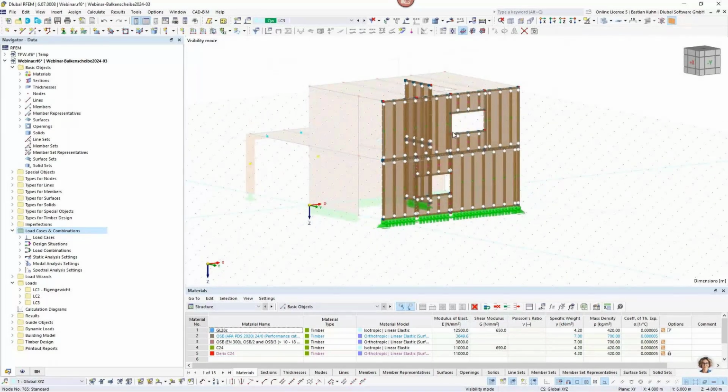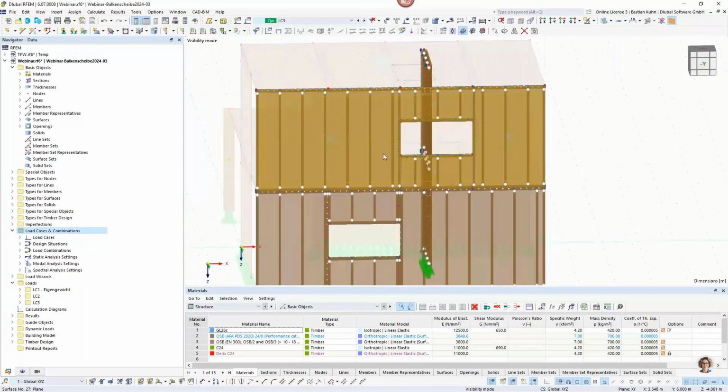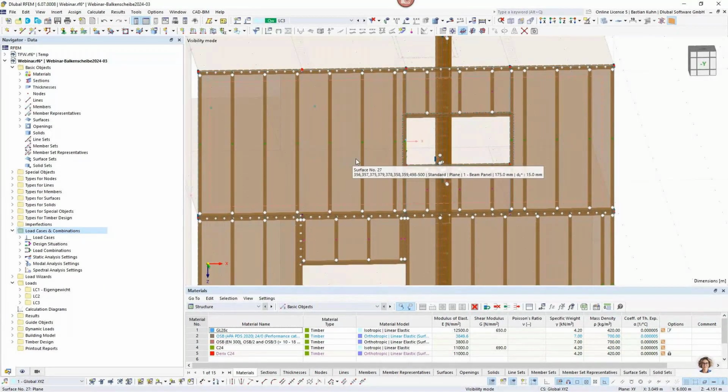But anyway, okay. So now we look at the top wall first, and we see that the distribution of the beams and posts is quite good. We would calculate the opening, and it kept our spacings of 625 millimeters in between, and here we have a middle value of 100 millimeters left, and this is also good because we still can get insulation into it here.